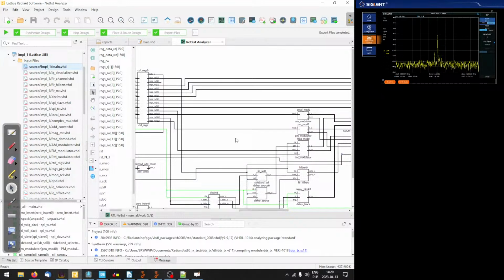So what we have to do is we have to add a signal generator somewhere between the register and the frequency modulator. Sorry, it's this block, not this one. So we have to create a block that's going to generate the tone for the CTCSS.